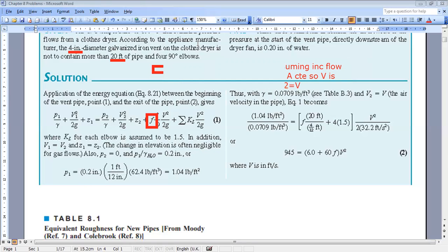Yes, in general, what are V1 and V2? Okay, in general, V1 is the inlet velocity, V2 is the exit velocity, and this V is the average velocity through my system. But here V1 is equal to V2, so V average is equal to V1 and V2. Okay, so when you calculate losses, it is the average velocity. But here all will be equal, V1 and V2.